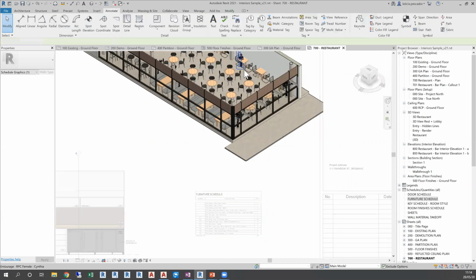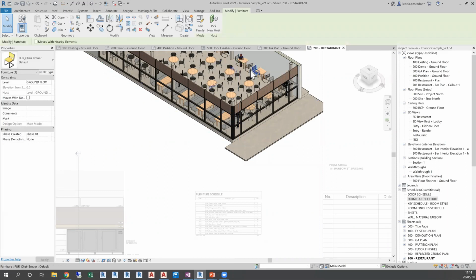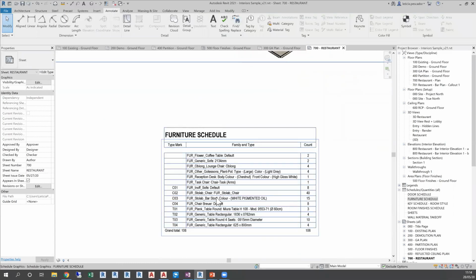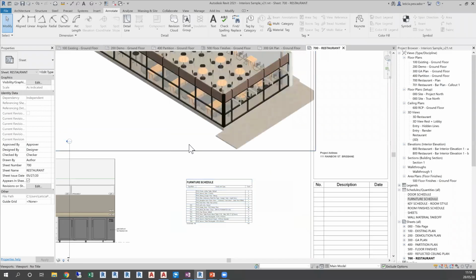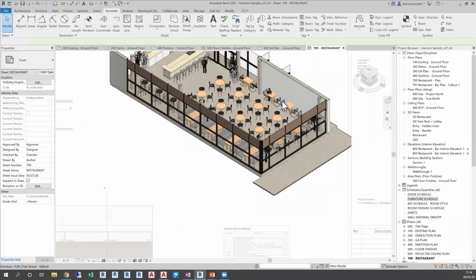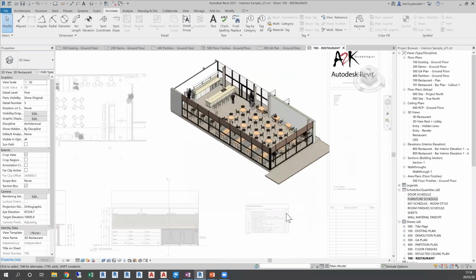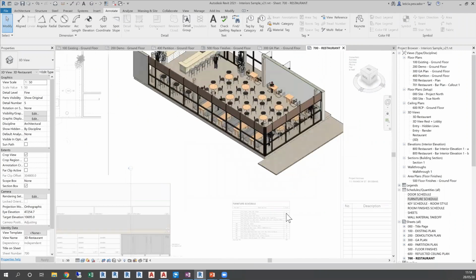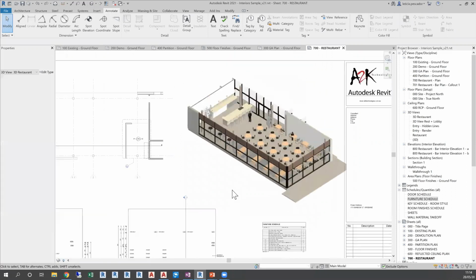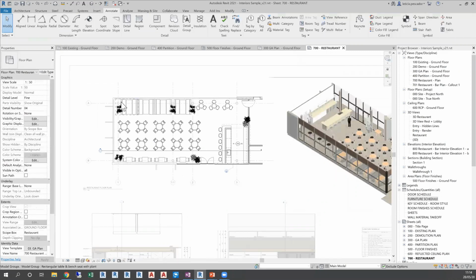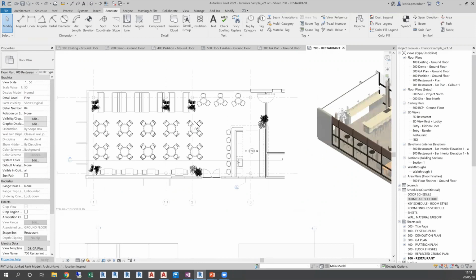Which means if I go here and I select this chair, which is my chair row within my schedule, this is what corresponds to that chair. If I start deleting an object, I select and I delete, the quantities for the schedule will automatically get updated. In a similar way, we could add the room names automatically within views.